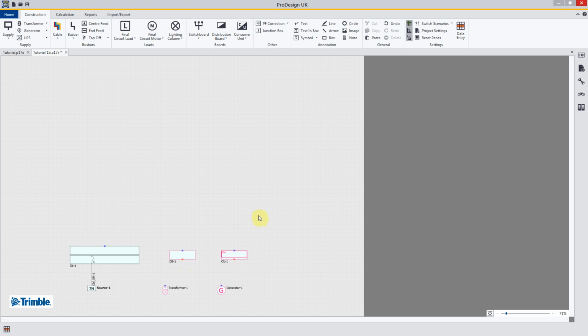It's important to note when you start a project to denote your source from top or source at bottom. If you have the wrong connection set, then you will get permanent issues with trying to connect the network, because what you're in fact trying to do is to connect load connections to load connections, and as we shall see, that will give you errors.